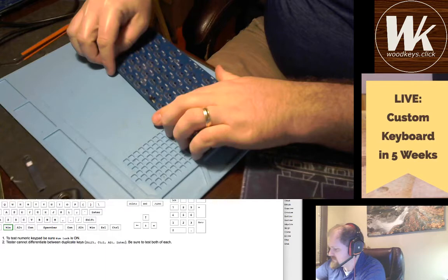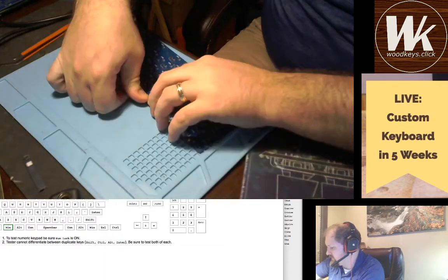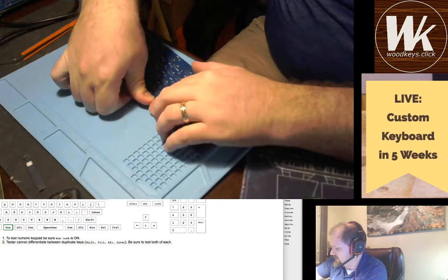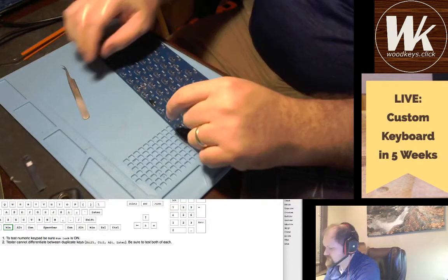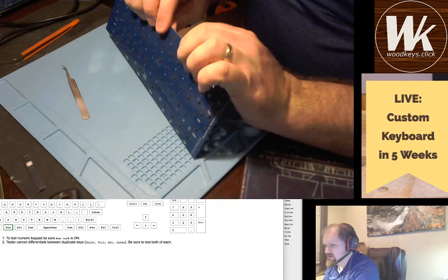we start trying to do this with solder paste. And obviously, if we sent this off for pick and place assembly, the robot's not going to have that much force to push down in there. So we do need to identify, before this can go to manufacturer, what the problem with that is. For now, all we really have to do is just make it work.